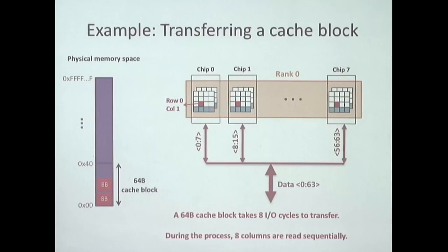So you basically need to do 8 transfers over the memory bus. During the process, you read 8 columns sequentially from the different chips. So that's how it works. There's no magic, basically, in the end. I mean, this is very simple right now, hopefully, to everyone.